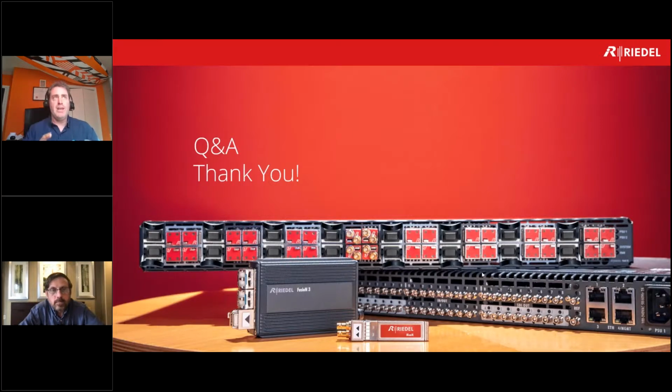So then you have to think about how many you want to scale. If your equipment can do UHD, how many you want to pass in, how many you have in your studio. So the switch for me will be the last thing you do. You will count the number of JPEG XS or the number of 2110 streams you need, and then you move to the design. I don't want to plug that, guys, but I did some videos. You can look at Renault Talks IP. There's nothing on products there, but you can find the 2110 versus 2022 video, and also we will push monolithic switch versus spine leaf. Great, I hope I answered your question.